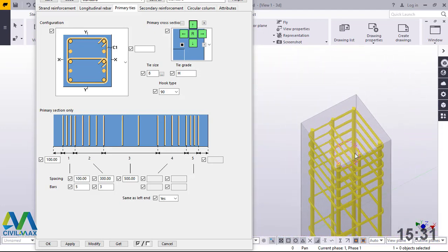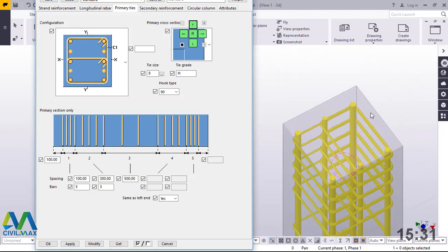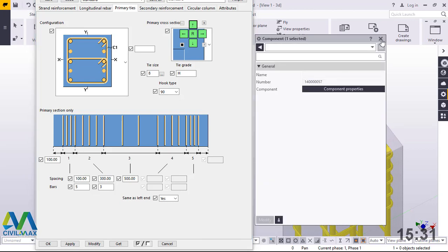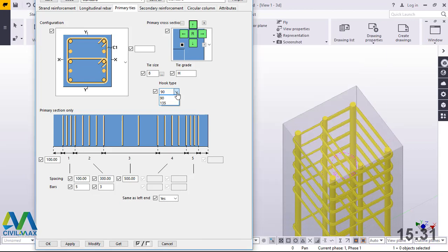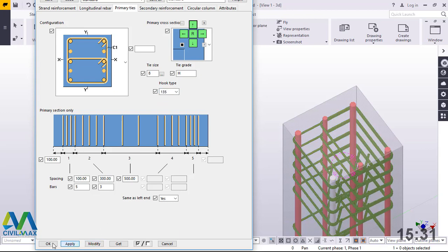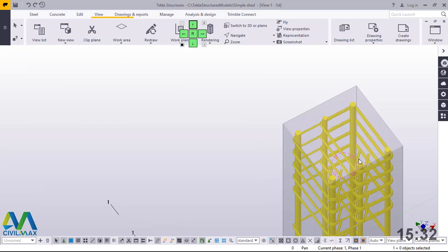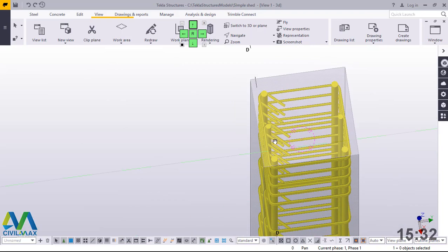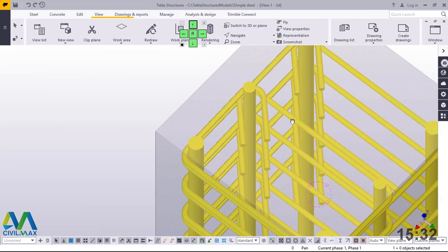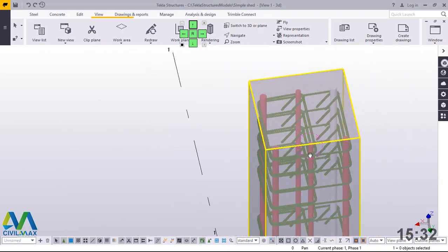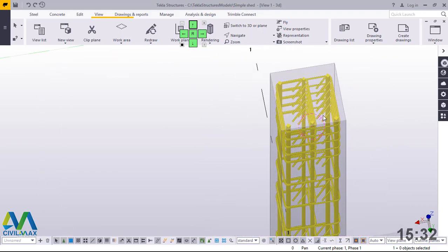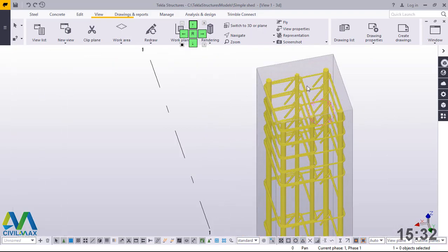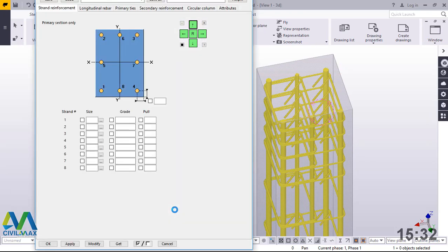See, we have no bends. We can change that. Double click on that and come all the way here and click that angle 135 and click OK, modify, and it will respond to the settings you've just typed in. Now that is how to do that. And once you've done that, just double click once again for us to access the setting window.